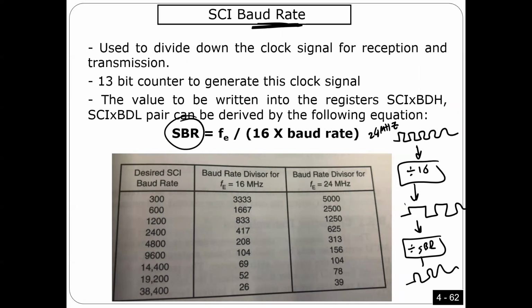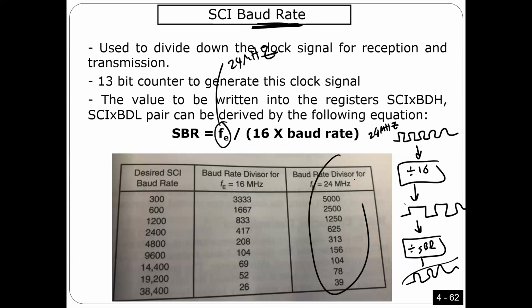This frequency is the transmission rate. That means in every cycle you are going to transmit 1 bit. You got what I'm saying? So if you follow what I said, this is the system clock, 24 megahertz. In this table I have two values, one is 16, one 24. I'm assuming we are going to work at 24 as usual, so I'm going to focus only on this column.